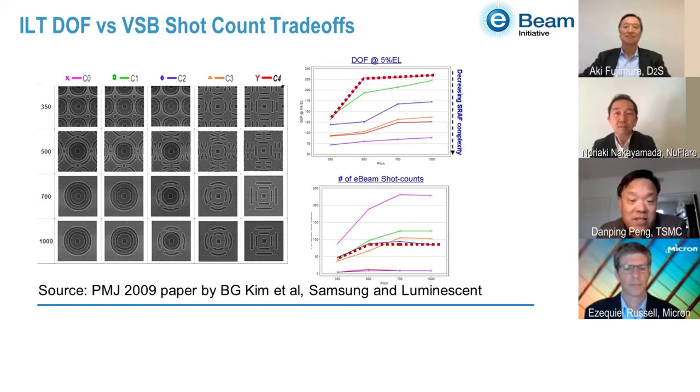And I think today, with GPU acceleration, we can address the long run time to get the ILT solution. With the multiple beam mask writer, we can write the mask with any complexity in constant time. And also, with the acceptance of ILT mask solutions in leading nodes, we understand what type of MRC rules we need to use.